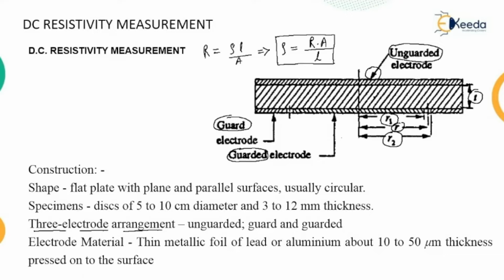Then we can use the equation from the reference: R is equal to R1 plus G upon 2 minus delta, where delta by T is equal to 2 by pi ln cosh of pi G upon 4T. So these are the equations that we have to use.